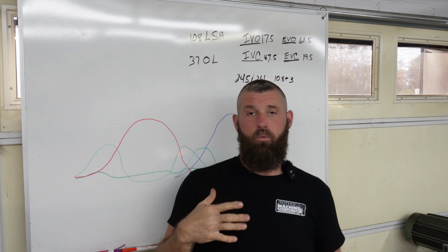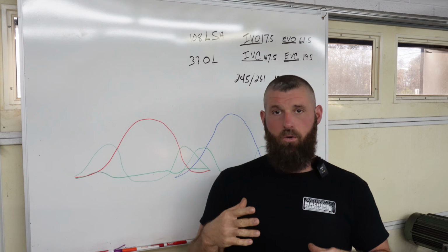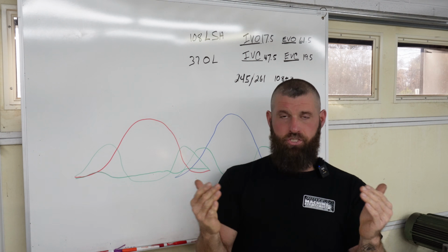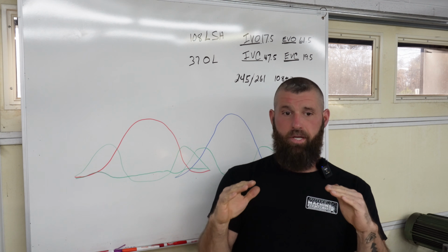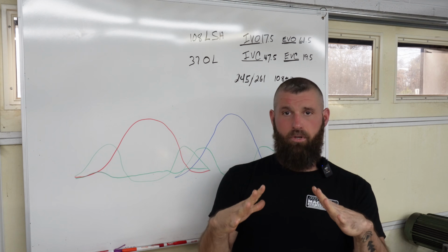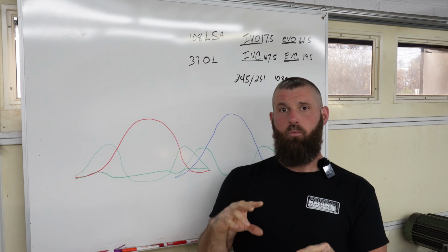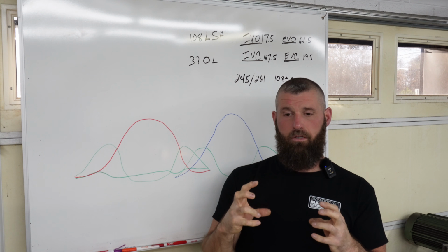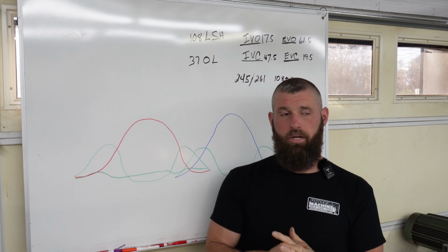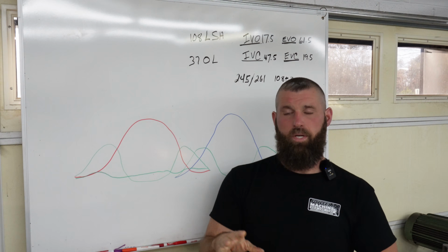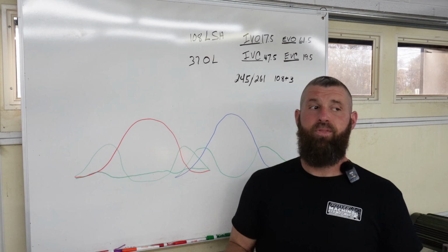So what we have figured out is a shape to the acceleration curve that will allow us to run a little more acceleration without the lobe going inverse radius. We did that on the original cam.